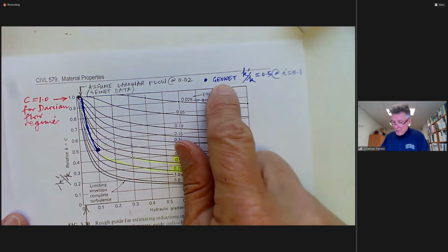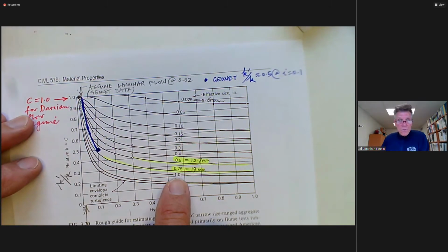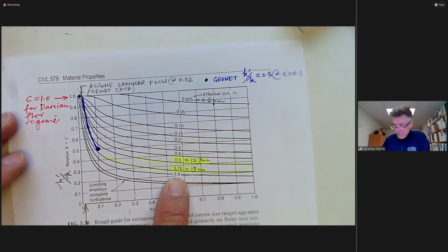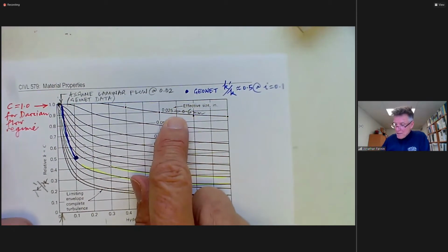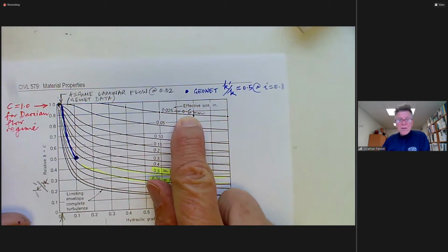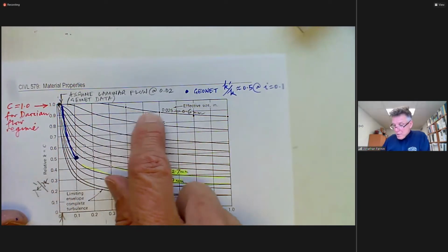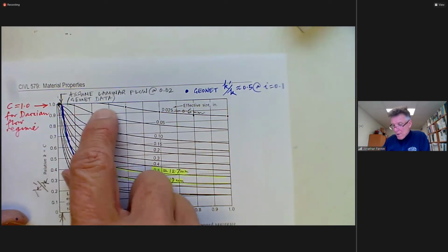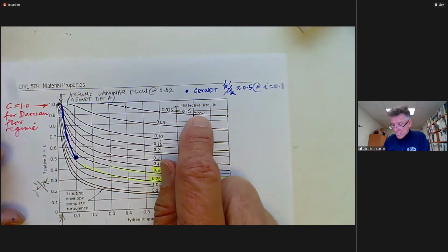And we see two things. First up is this reminder that not all soils exhibit Darcian flow. Indeed, if we went back and looked at the data here, this would imply if the grain size is much greater than about 0.5 millimeter, you're going to entertain not a major impact, but you're going to entertain some element of non-Darcian flow.